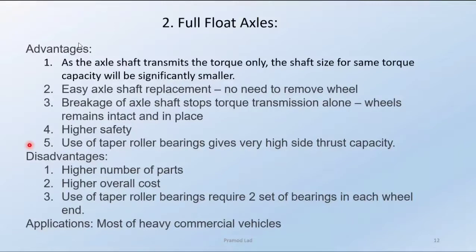So let us see what are the advantages of this type of axle. First, as the axle shaft transmits the torque only, the size of the shaft for the same torque capacity will be significantly smaller.